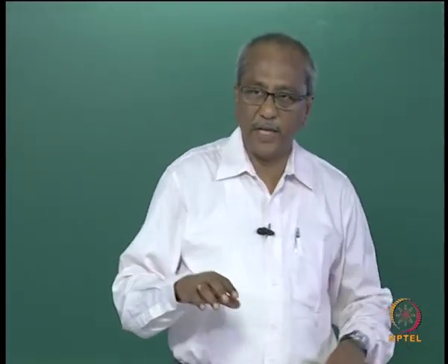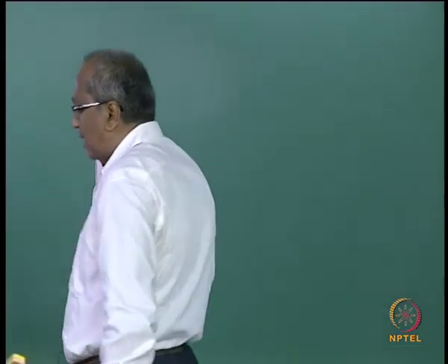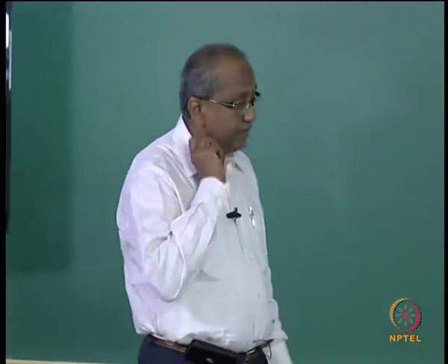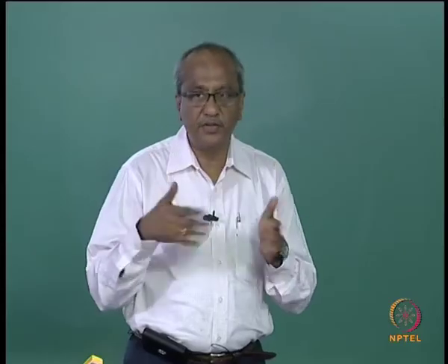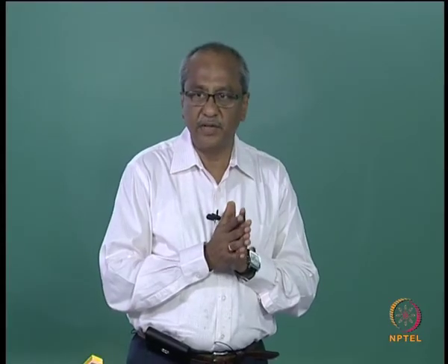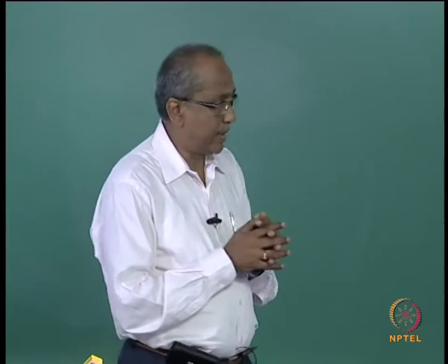So then in that case what happens, you have tension created, and in due course over a period of time it gets torn, and then once it gets torn or punctured, then it is a problem. Other serious problem, once it is damaged somewhere, you need to have immediate rectification. If you fail to do that, then that leads to catastrophe. That is the biggest disadvantage with geosynthetic products.